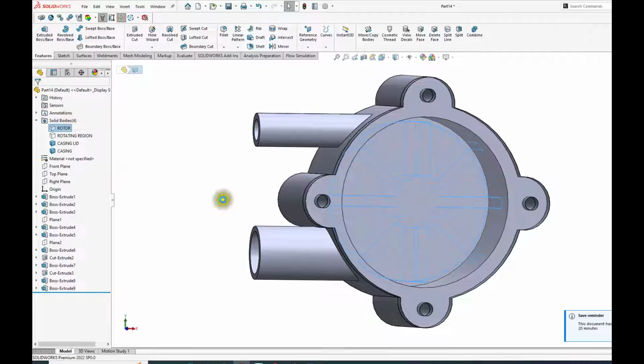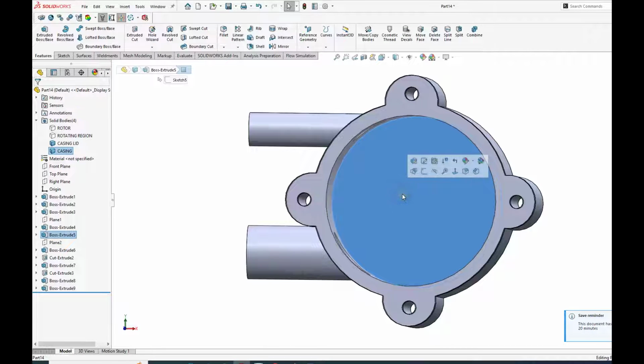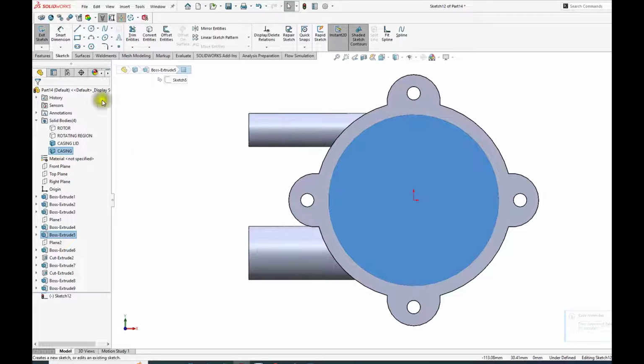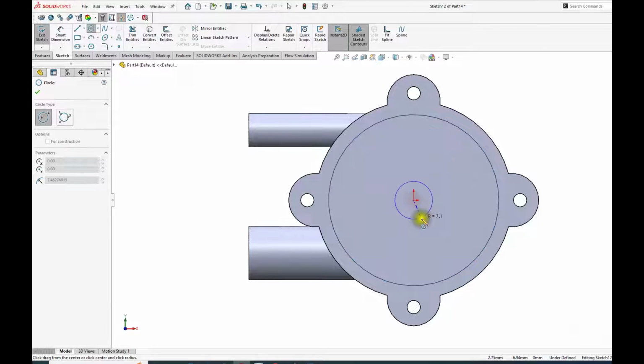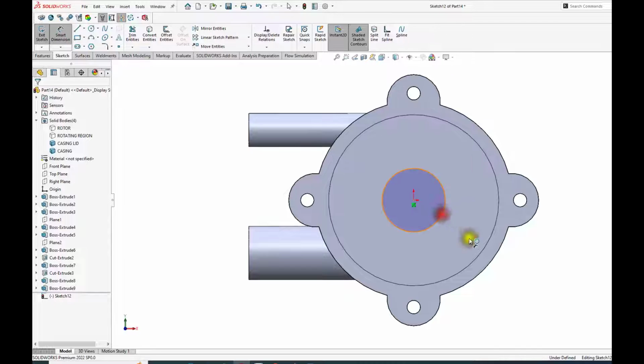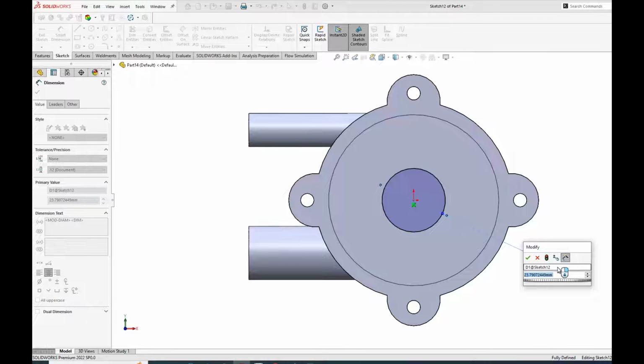Let's hide the rotor, and now on this surface is where we're gonna locate, in this case, the ball bearing. On that center, the ball bearing diameter is about 22 millimeters. Here you need to do a small print, most 3D prints, a tiny bit, just to be sure that it fits, because you don't want to sand too much.